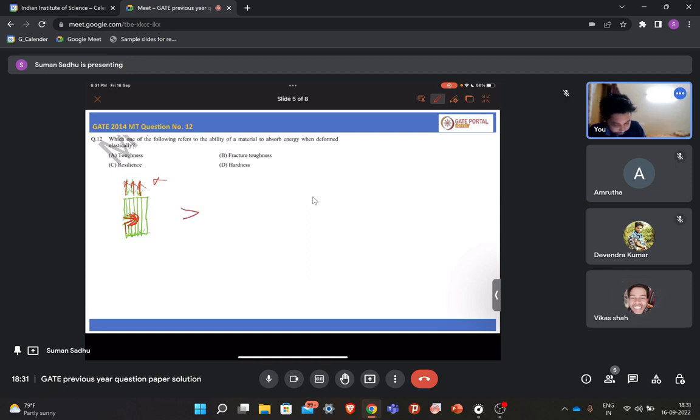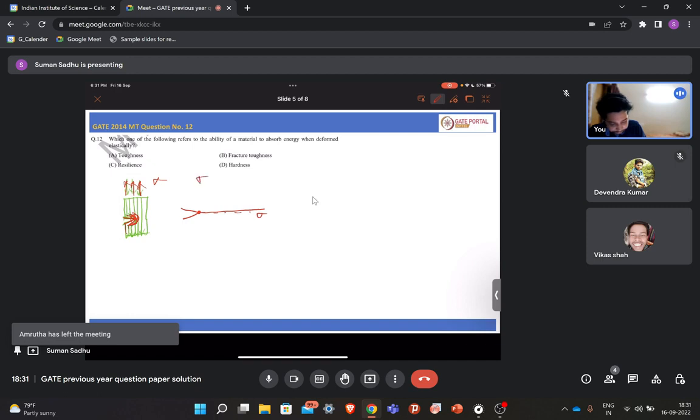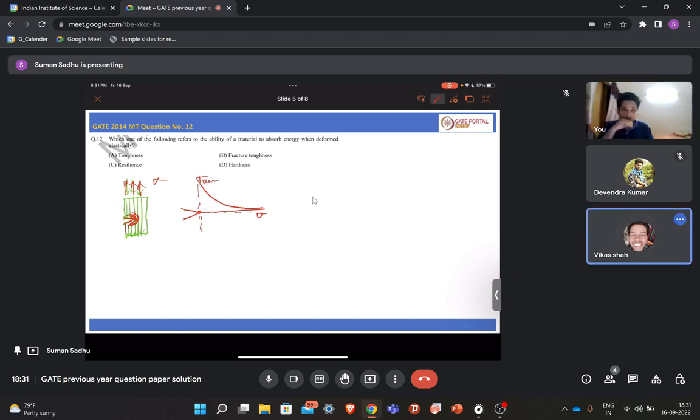So that is why, let's say you are applying sigma here, and now this is your crack. At a very far distance from the crack, your stress will be sigma, but near the tip the stress will be very high. Let's say it is sigma max. So your stress distribution will be like this from the crack tip. You are applying sigma, but the stress accumulated near the tip will be very high. So which portion will try to deform first? This tip region, right? Because the stress is very high there. So that is why it will deform and then propagate.